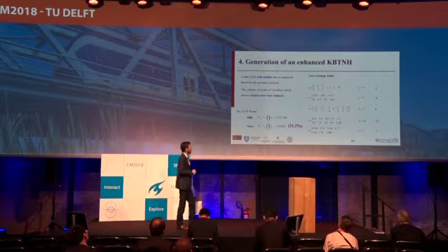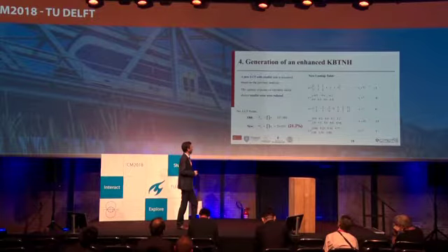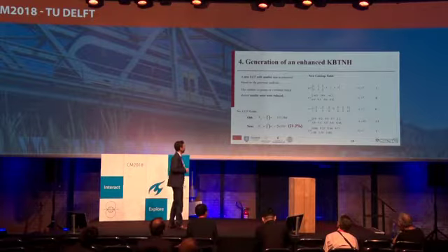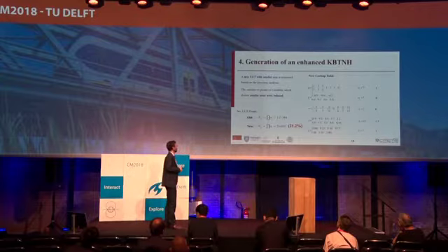Same number of values for the direction of the non-dimensional creepage. We decreased the number of values for the magnitude of the non-dimensional creepage, because we could see that, especially for large values of this parameter, the interpolation was very accurate and did not cause any problem, and one value less for the non-dimensional spin creepage, resulting in a new table size of 24,000 compared to 113,000.